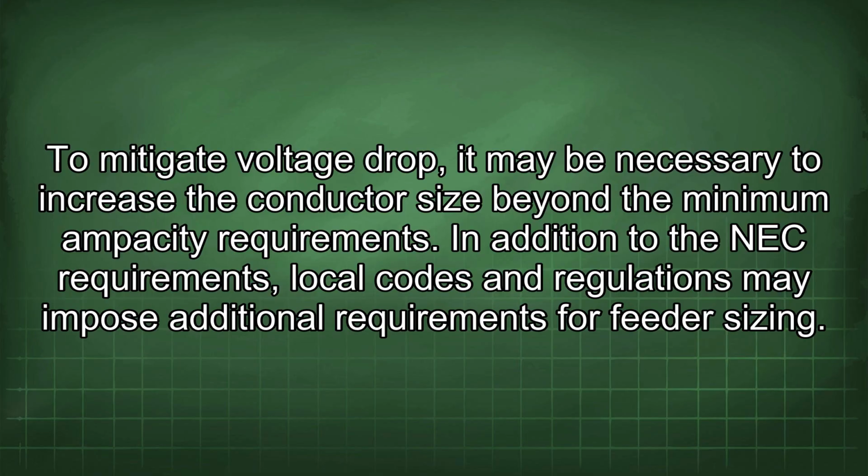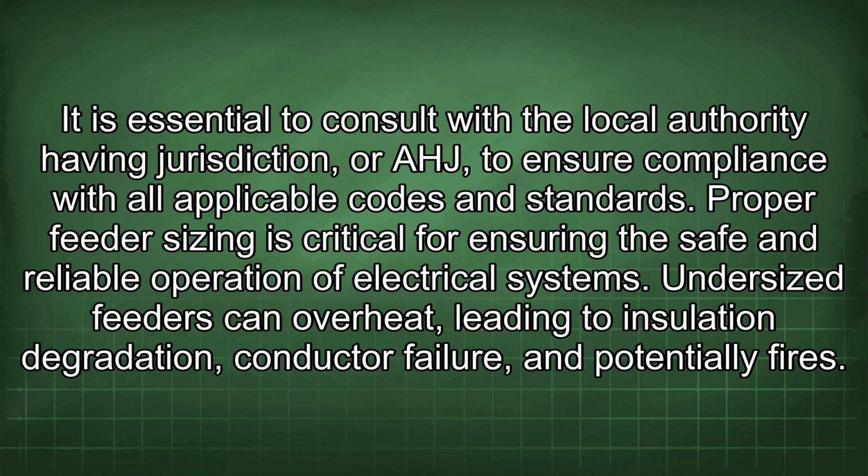In addition to the NEC requirements, local codes and regulations may impose additional requirements for feeder sizing. It is essential to consult with the local authority having jurisdiction, or AHJ, to ensure compliance with all applicable codes and standards. Proper feeder sizing is critical for ensuring the safe and reliable operation of electrical systems. Undersized feeders can overheat, leading to insulation degradation, conductor failure, and potentially fires.